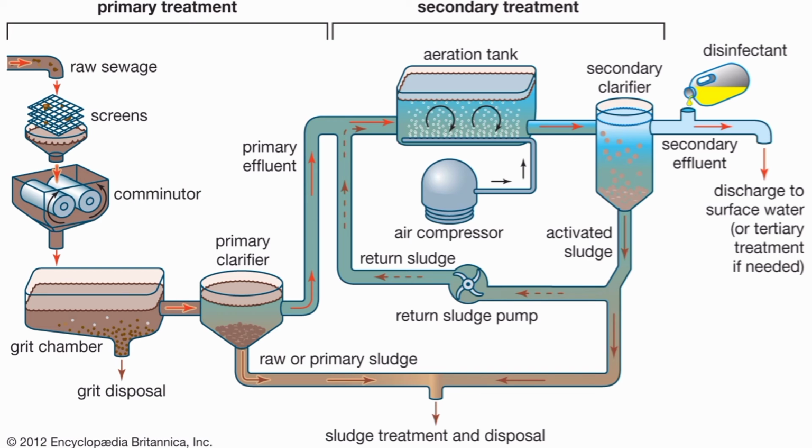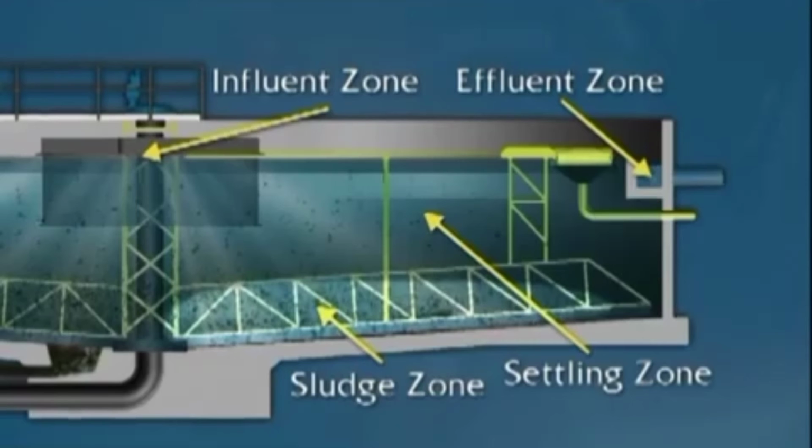The solid particles of the sewage tend to settle down due to gravity. However, most of the solid particles of the organic compound remain in a suspended state in the flowing sewage. If the flow of sewage is stopped and it is stored in a tank referred to as a sedimentation tank, the solid particles can settle down at the bottom.